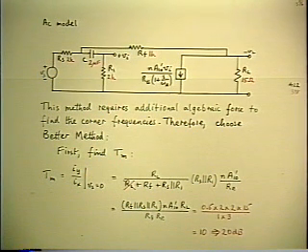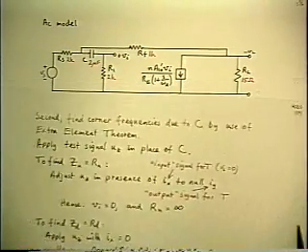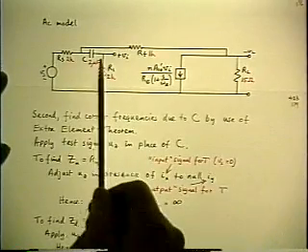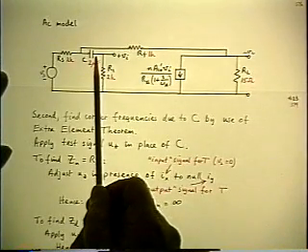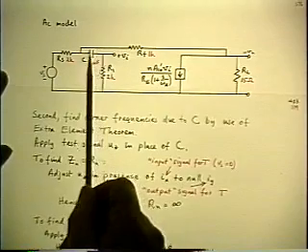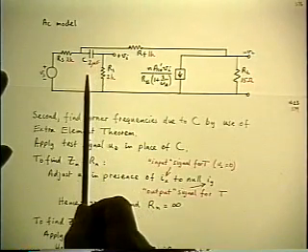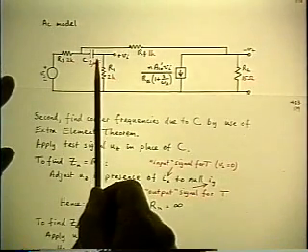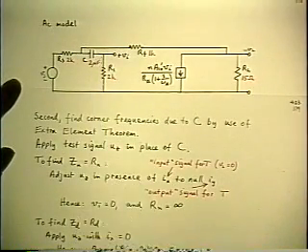Now we have to replace the capacitor. Again, we can do it all in our minds, applying the correction factor for the theorem. If we replace the capacitor with a second test signal, we have to calculate two driving point resistances, Rd and Rn. Rd is found by applying the test signal single injection and making the input 0.